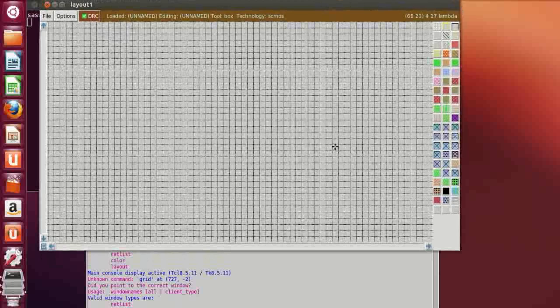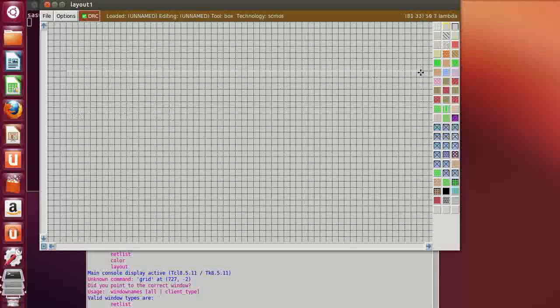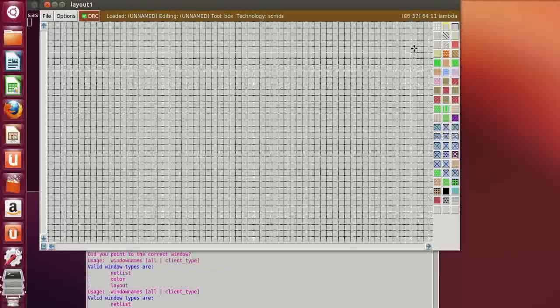So if you want to draw the layout from the twisted schematic, then it's very easy to draw. First we have to draw the PMOS, then the NMOS. Since the function is A plus B plus C, the OR operation, the PMOS are in series and the NMOS are in parallel. When there's a series connection, we can place one whole N well at a time.